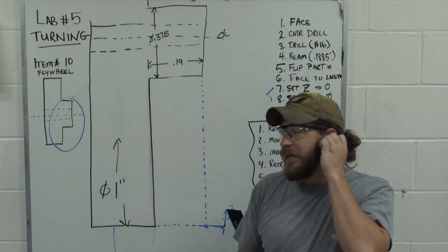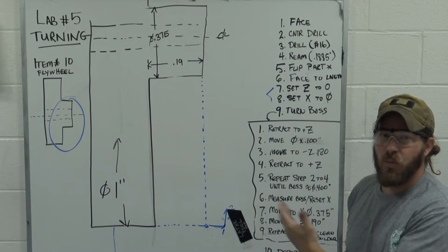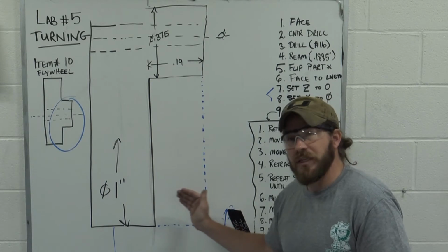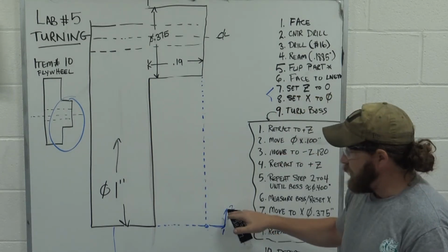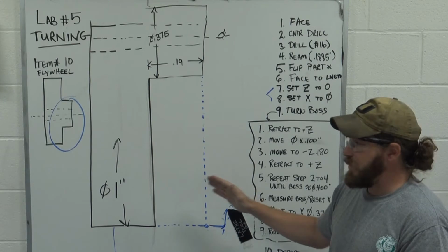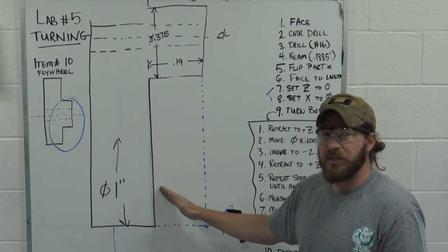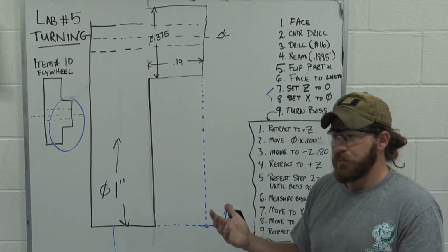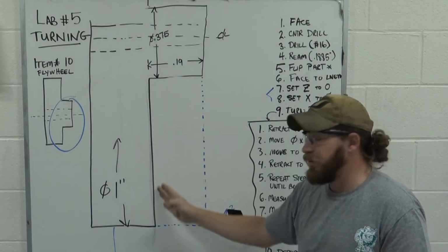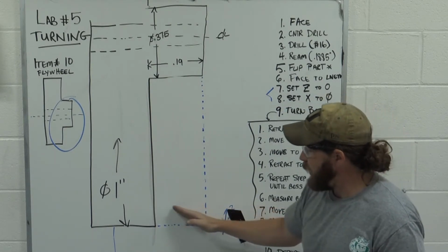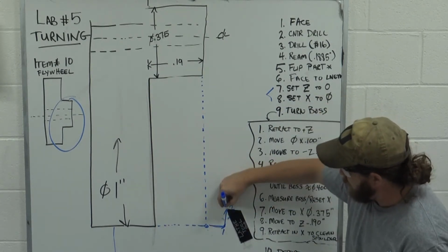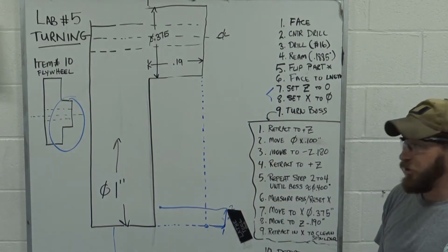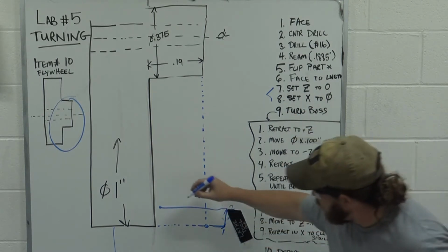You're probably wondering why, since that doesn't seem to make sense. We should go to 190, right? The problem with going to 190 is that your tip will actually end up making a weird design on this shoulder. We want to have a nice clean shoulder after all this is over with. So when we go in here, we're going to stay at 100 and just Z into 180.